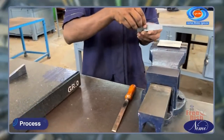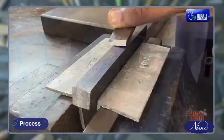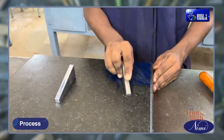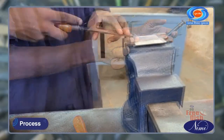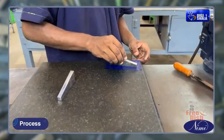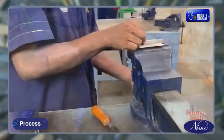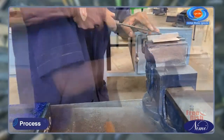Hold the job in a bench vise, scrape and remove the high spots with a flat scraper. Repeat the process until the Prussian blue covers the entire angular surfaces of part 1. Similarly, scrape part 2 and maintain the angular surface without high spots and angle 19 degrees 17 minutes.